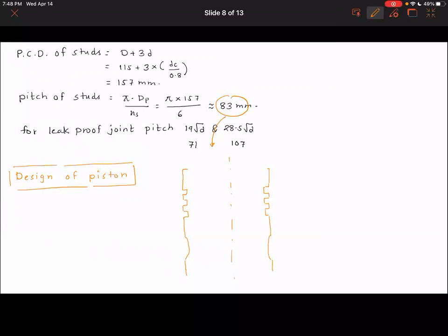And internally, if you look at the piston is hollow, but its shape is unique in a sense that you will notice that there is some sort of a dip on the top of the piston. And this top of the piston and the cylinder head actually make the combustion chamber.